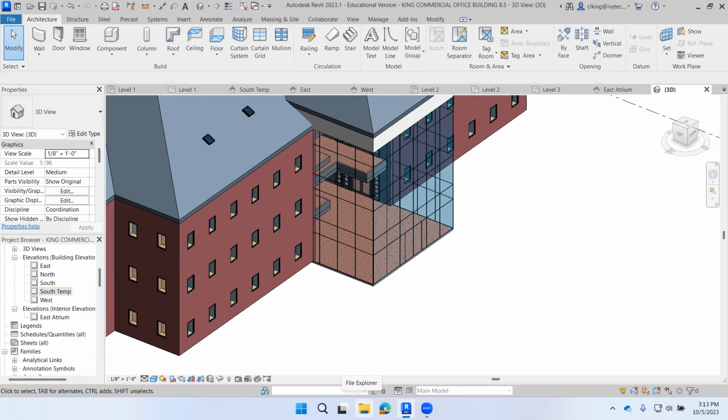As you move the cursor while placing the horizontal grids, you should see the grid snap to the grid around the corner. That is when you click the mouse. Drag your cursor on the view cube to see your project from different views. Clicking the home icon instead when your cursor is over the view cube will reset the view.